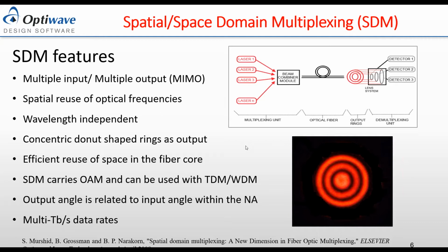Instead of being a meridional ray flowing through the axis of the fiber, they take a non-meridional path and follow a helical path inside the fiber, and appear at the output end. If you took a screen projection of the output, it would look like concentric rings.